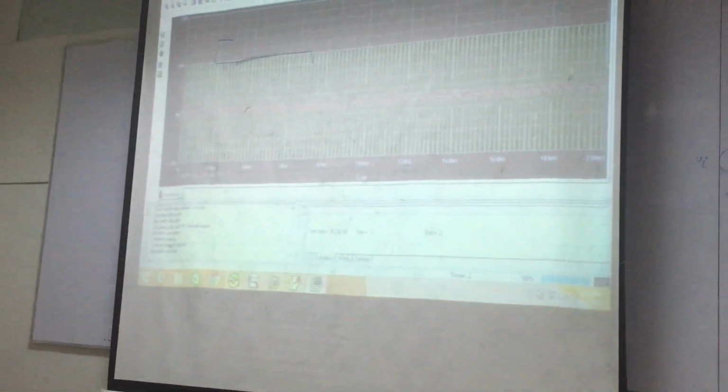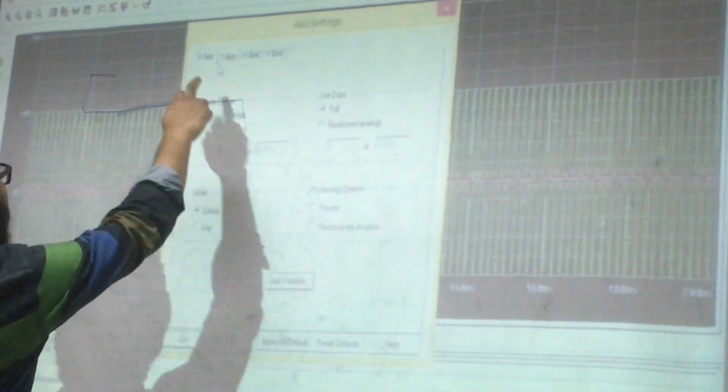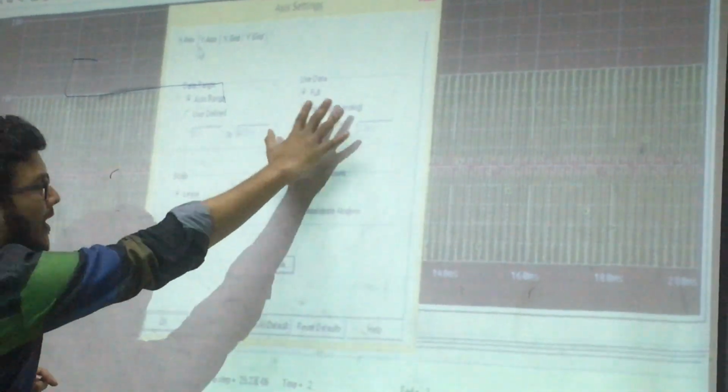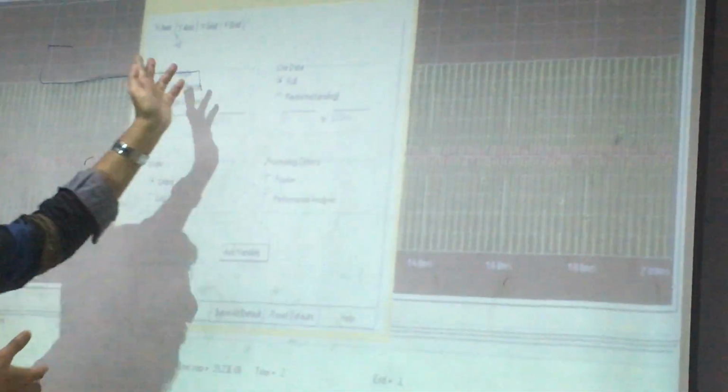You go to plot, you go to axis settings, because I can use the time information for the last 5 cycles in order to refine it. So I'm talking about the axis, that's why I need to go to the axis settings. Again, two axes are there, X and Y. I need to work on X, told you already. So the X axis is already selected. Forget other items, you need to work on data range, because we're talking about values.